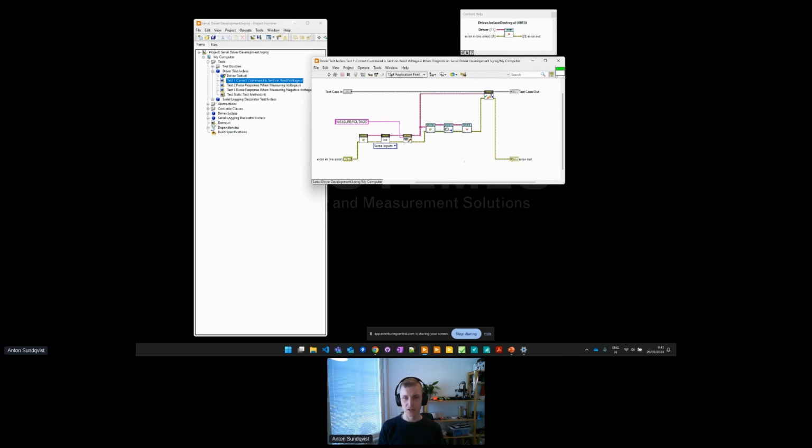I would just create the APIs so that I have something to test against. And then I need to check that the serial port has been called with the proper message here. And this now could be something that I get from a manual. I might not have the instrument yet, or I could just play with the instrument on the bench and send some serial data to it to check how it behaves. But now I can then define how my driver for this instrument should behave.